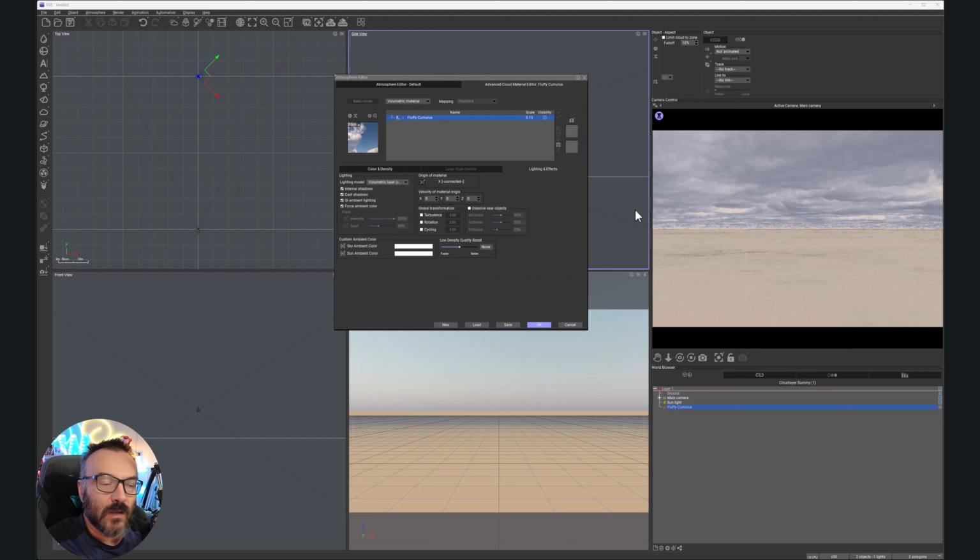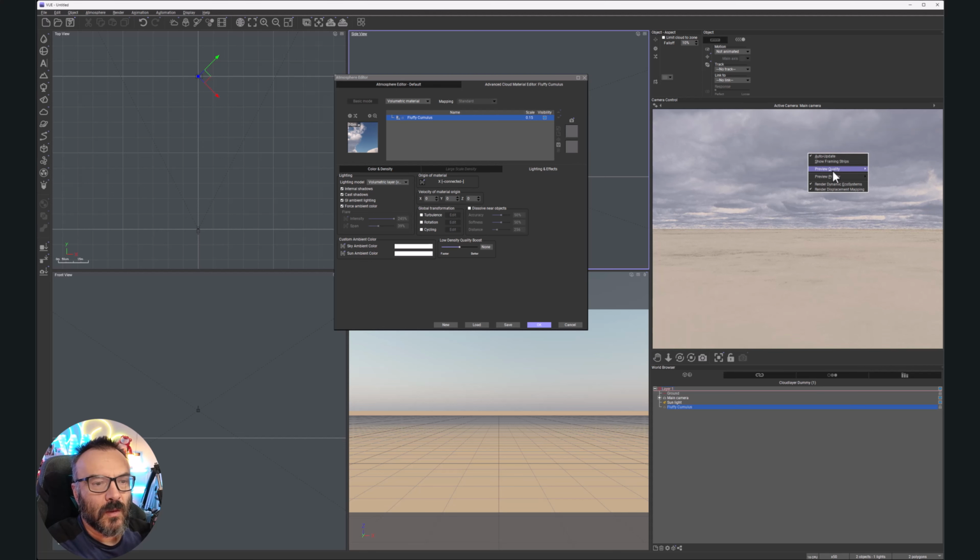And by the way, if the preview quality as we're looking is not up to what you want, and you want it a little bit better or a little bit faster, you can always right click on the menu with the main camera, and you can select preview quality. Currently it's at standard. You can switch to fast, which won't render everything, and you can notice we have, see those dots? It's what I was saying, it's cutting off some of this, but it's quite a bit faster and less loaded on your computer. So if you work just with shape or positioning, this is maybe a better way to go.